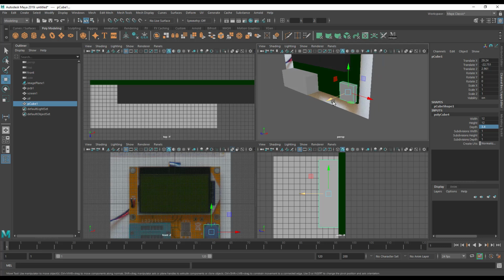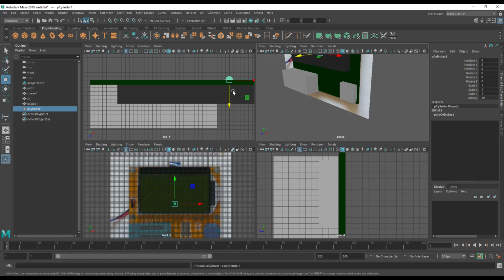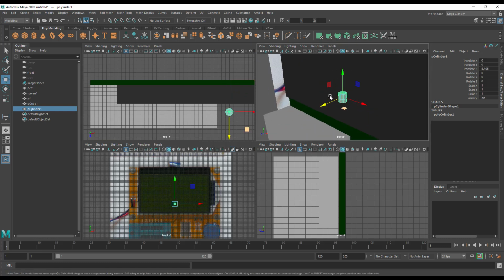So we've got the base of the button. We now need the circular part of the button. So I've measured this here, and the circular part of our button at its maximum width is 12.6. So I'm going to come in and I'm just going to create a cylinder, which I can focus on here, and now I need a radius at 12.6.